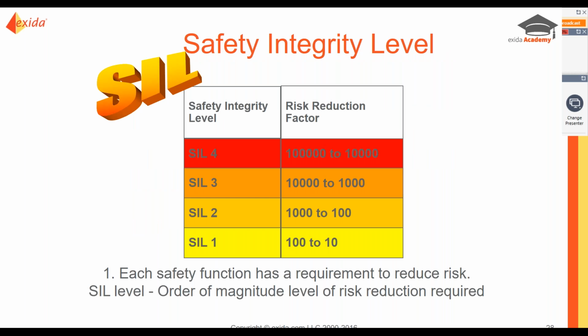You take that number and open up IEC 61511 and see this safety integrity level compared to risk reduction factor table. And there are two ways to interpret this table. First, you can be a little conservative and say, well, I need a SIL2 SIF here, because for a SIL2 device, that's going to have a risk reduction between 100 and 1,000.